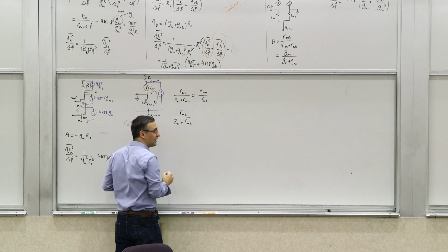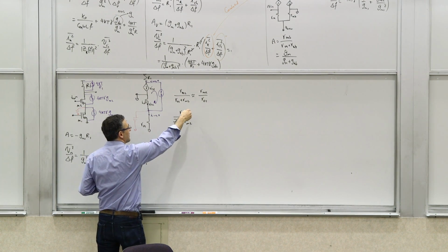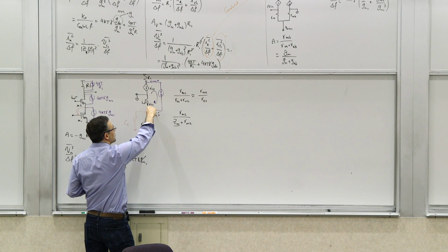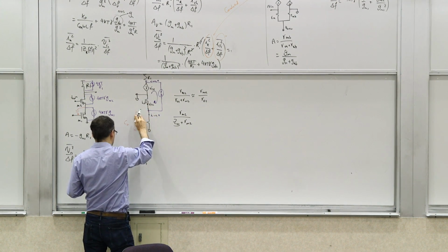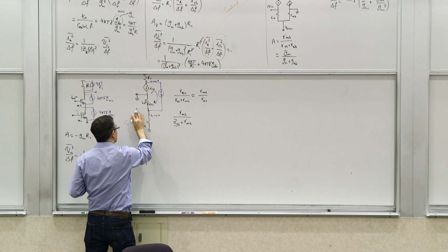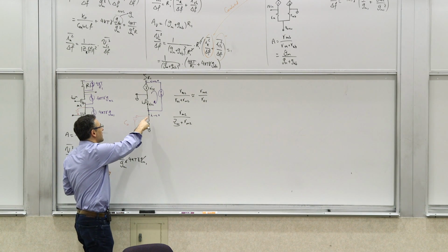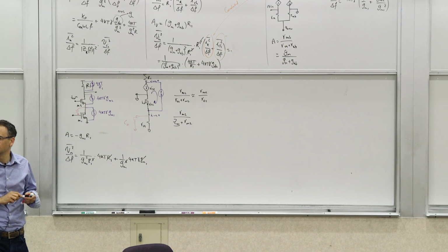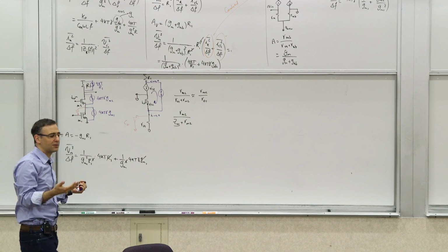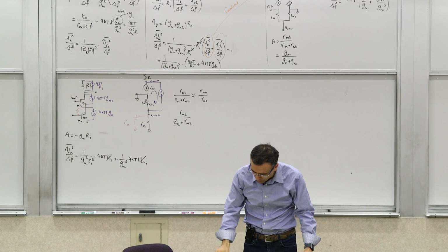As ZO1 becomes smaller with frequency, this division ratio becomes larger, so more and more of the current can flow in this direction, which means this current is not going to be zero anymore. It starts contributing to the system, and you can calculate how much by just calculating this ratio. So that's one other thing.